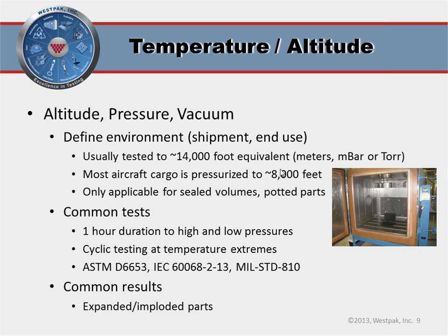One other common issue with products like our laptop is that at high elevations the air is thinner. The laptop uses air to cool itself, and therefore it has less effective cooling. So a good test to run where you have a product that generates a lot of heat or uses air to cool itself is to do a full stress test at maximum operating at high temperature at a high elevation to see if the product can still effectively cool.